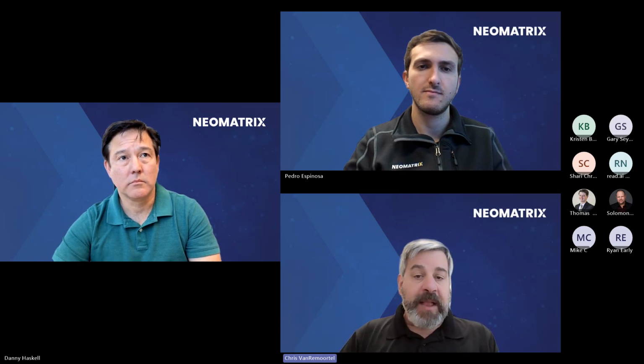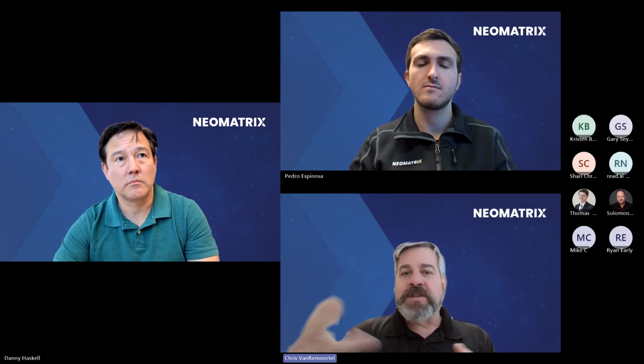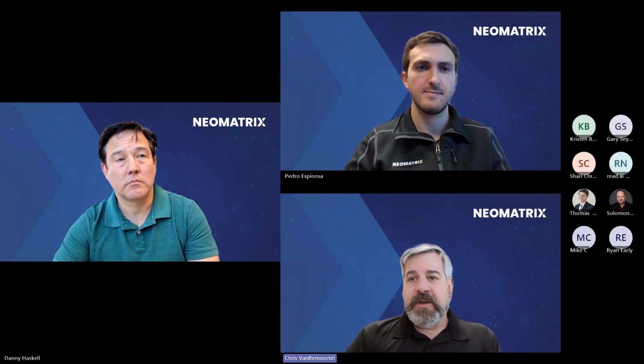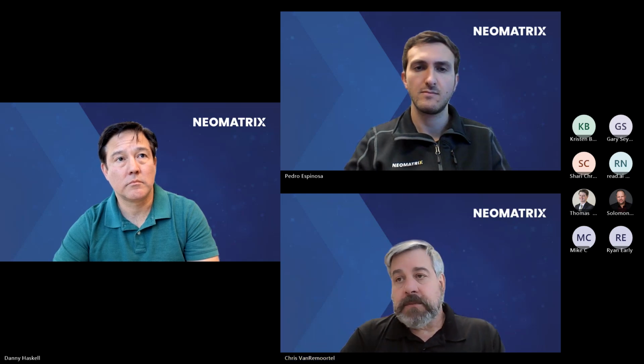From an OEE standpoint, all of those specific faults have the type of unplanned downtime, so we still can calculate our OEE, we can still show it as a color of red when it's faulted, but then we can have analysis tools to go, hey, show me these states and give me an analysis of all the faults, what's the most prevalent fault? So basically you're doing state analysis on a subset of states.